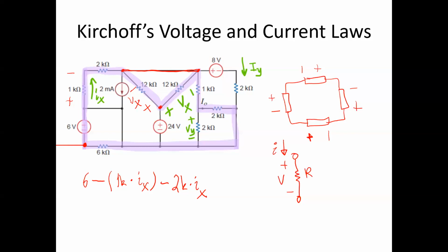So there's two ways that we can now proceed to go about writing Kirchhoff's voltage law. Either you can say, hey, there's a short circuit connection here. So if I just directly go across that short circuit connection, I can bypass both of those two resistors and just say a plus 0 when I'm going around the loop.